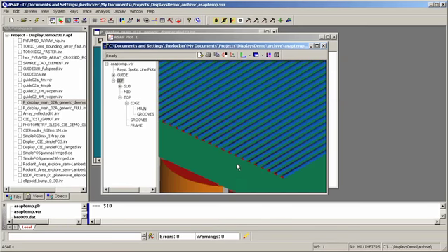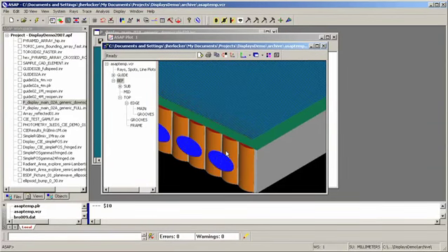Instead of having the light from each LED just plunge forward along the guide towards the other end, when we impinge on the top surface and we see these little ribs, it causes the light to be diverted to the side. And when we do a ray trace, you'll see some of that action.